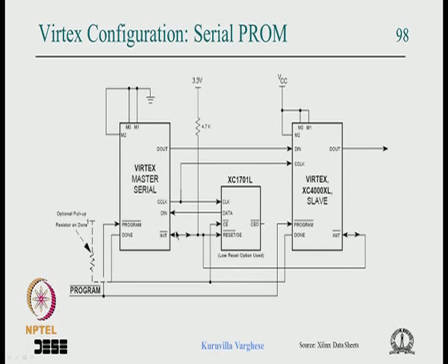So this init, which is an IO pin, an open drain which forms a wired AND, helps the init synchronization between the masters and slave. So ultimately every FPGA initializes and comes out of initialization, and then the master FPGA starts getting the data, okay.